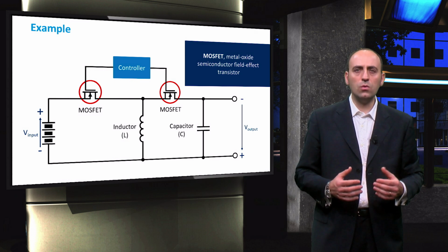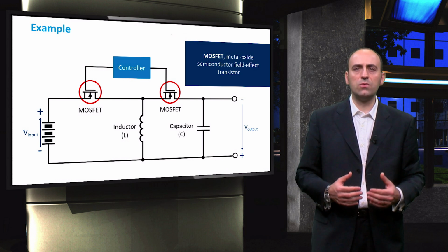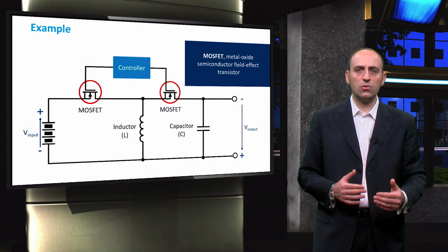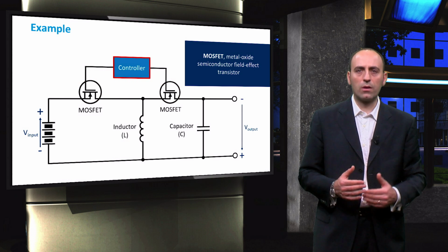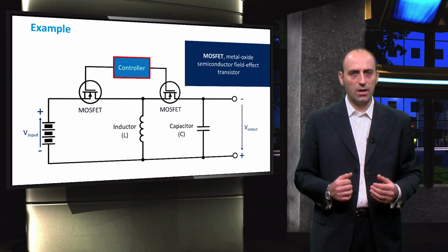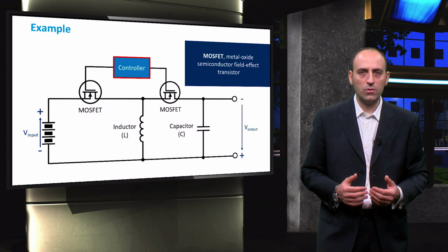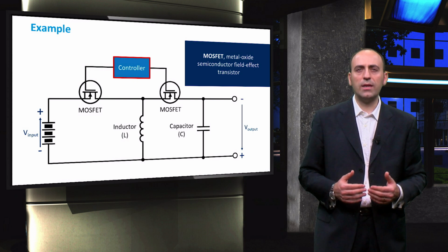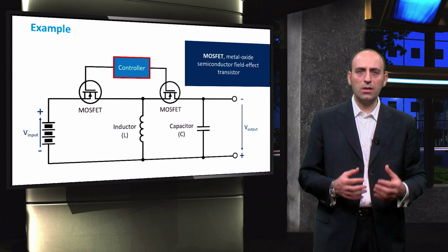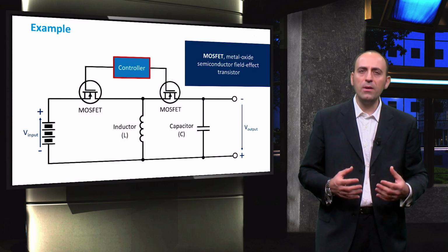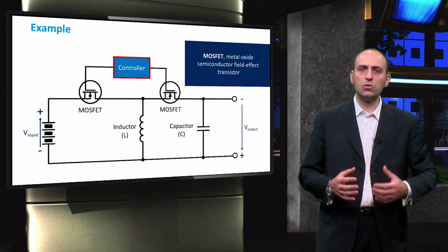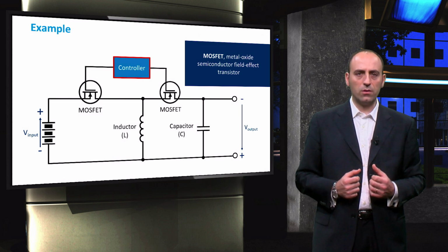The reason is to lower the production steps by just using the same device and set a controller to make the transistor work either as a switch or as a diode. The controller is nothing else but the maximum power point tracking algorithm, so it is usually a circuitry customized with a hard-coded algorithm, or maybe a programmable algorithm that controls these two parts of the converter.